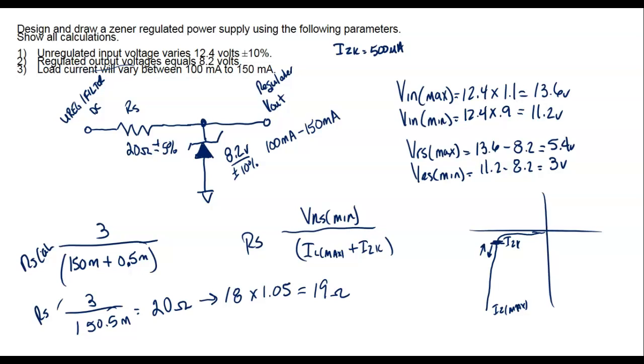Okay, so what else do I need to do once I calculate the size of the resistor? So what are the three things the resistors are rated? This is going to be on the next step. What's the ohm? Okay, well, power, wattage, ohm. Power, wattage is the same thing. You got me confused. Tolerance, thank you. Well, we got the tolerance, we got the ohm, so we got to make sure we're not going to burn this thing up, right?